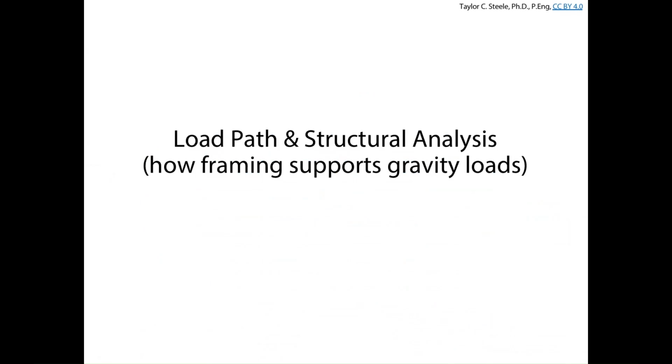So that tells us a little bit about what the engineer needs to do to communicate the design to the contractor. And once the design is communicated, we've gone through what the contractor is responsible for when it comes to actually building that structure from the top of the foundation to the underside of the concrete floor slabs. Now what's important for the engineer to really understand, even if you don't understand how things go together, is that once they're in their final shape, where do the loads go? And how do we analyze the structure so we figure out what the forces are? What are the bending moments? What are the shear forces? What are the axial loads in some of the elements?